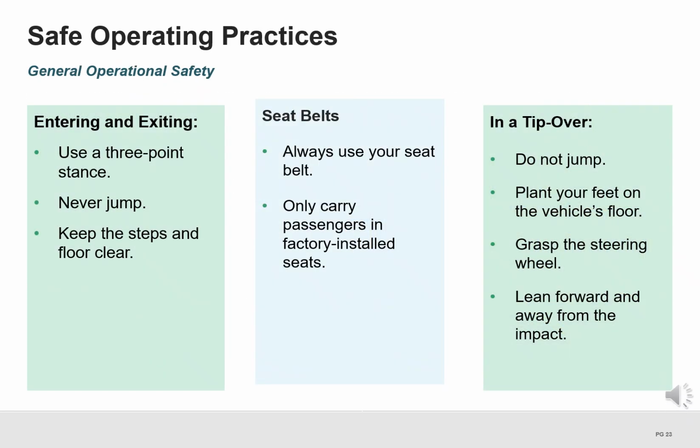Always enter and exit the forklift using a three-point stance. Never jump, and keep steps and floor areas clear. Always wear your seatbelt while operating the forklift. Passengers are only allowed if the equipment is designed with an approved seat. In the event of a tip over, do not jump.